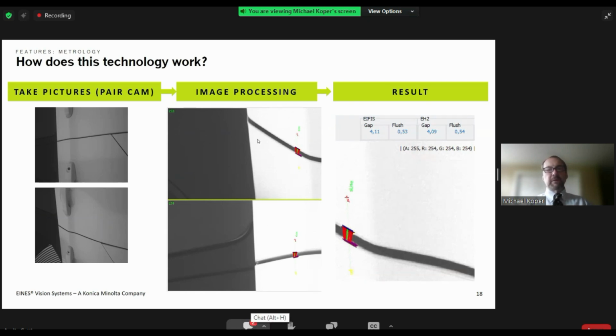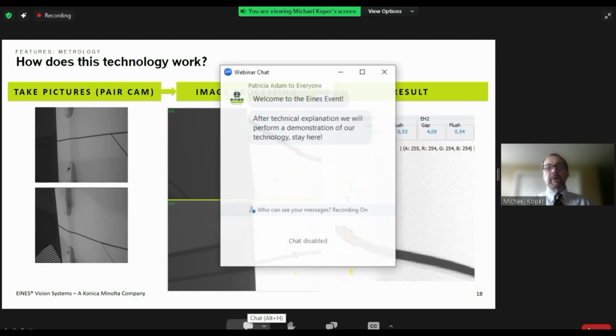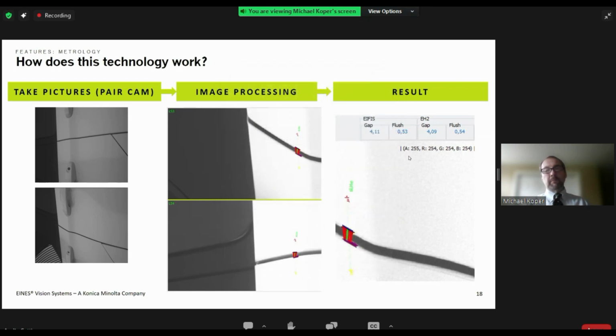And what we have to do in our process of correlating our system, while we have fixed cameras and vehicles go through the tunnel, is we also produce a handheld flush gap gauge reader, and we do the correlations. We can do it with that or a competitor model. What we want to make sure is that the flush gap measured with our handheld units is within tolerances of what our fixed camera is also measuring. And this is how we do our correlation process.